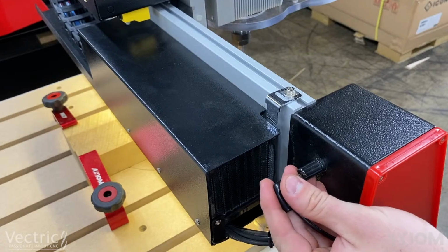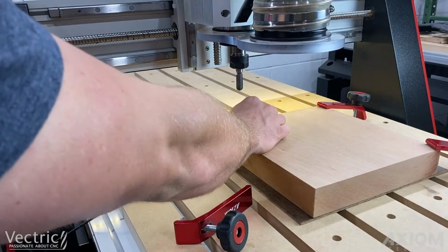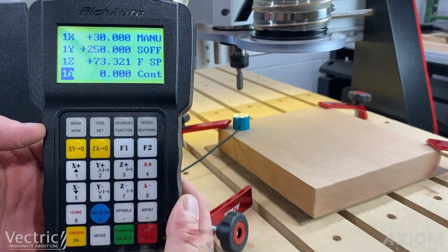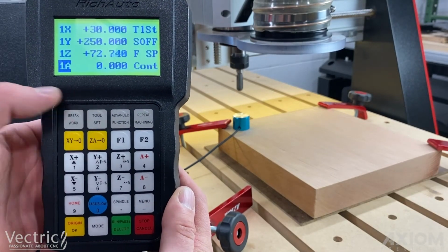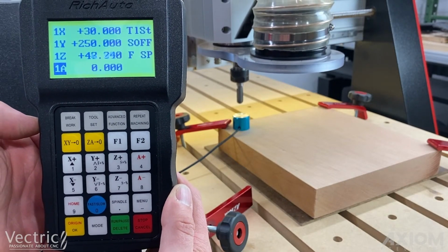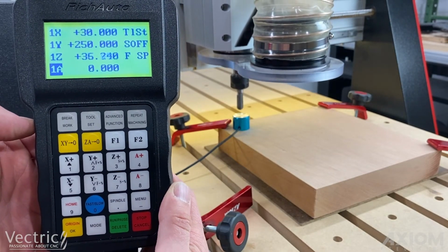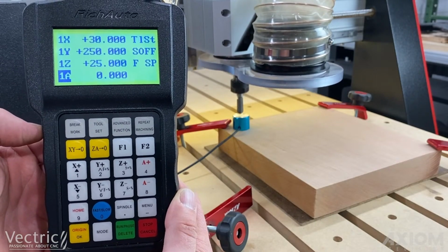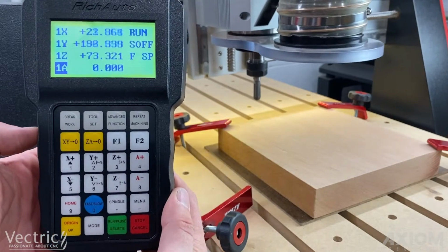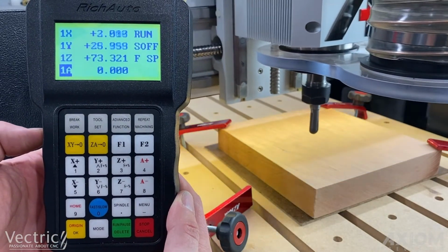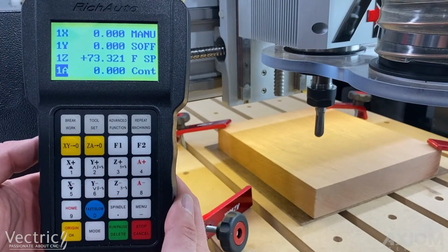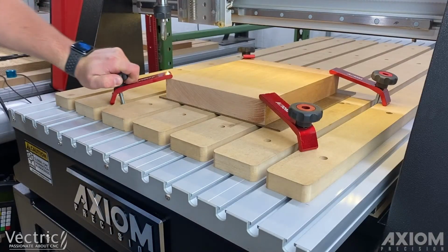Plugging in our touch-off puck, we're going to go ahead and touch off on top of the material. We're going to use this same position throughout the entire piece. Hitting the tool set button allows that to come down. At any time in the project, you can hit the OK button on the control. That's going to return us back to that origin point so we can just visually reference it. We can see that it's set at 0, 0. So at this point, we're good to go.